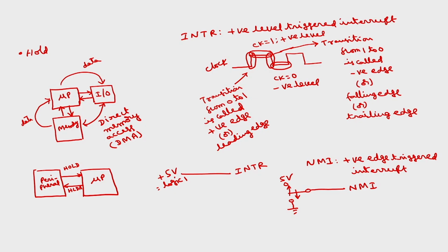Till now we have discussed all three types of microprocessor operations. The first one is the microprocessor initiated operations such as memory read, memory write, IO read, IO write. Second one is internal data operations, like storing of the data, performing arithmetic logical operations, testing for the conditions, sequencing the execution of the instructions, and storing the data temporarily during the execution in a memory location called stack. Then there are some externally or peripherally initiated operations, which are reset, ready, interrupt and hold. And the corresponding hardware elements and signals required for the 8086 we have discussed.